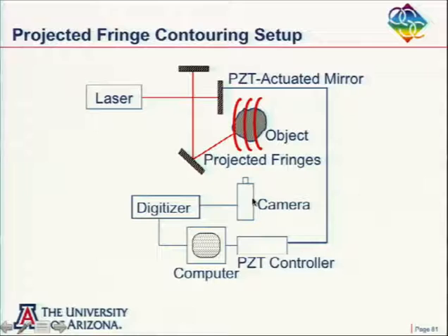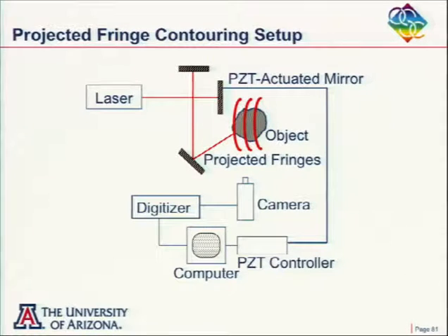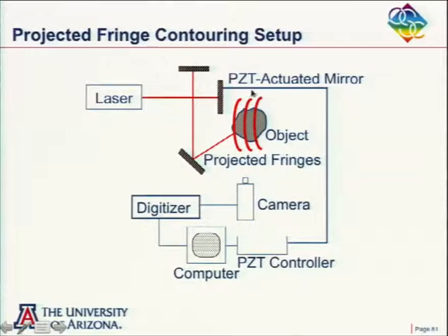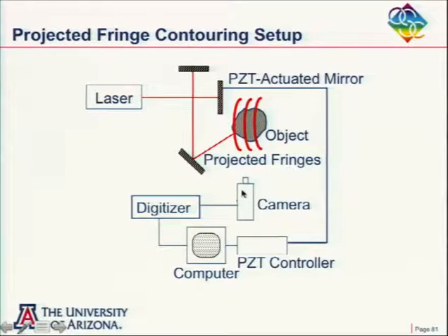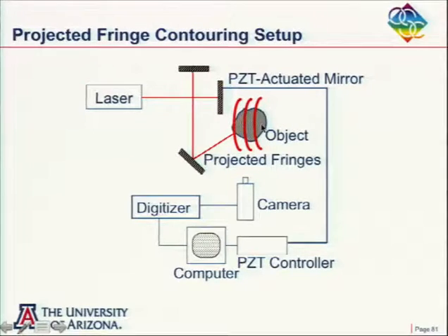And then I'm going to view these fringes down here, and I'm going to see this interferogram. It looks like an interferogram with some equivalent wavelength. And of course, I like to phase shift everything. So I could phase shift these projected lines here and use my regular phase shifting equations to calculate the height variation of the sample.